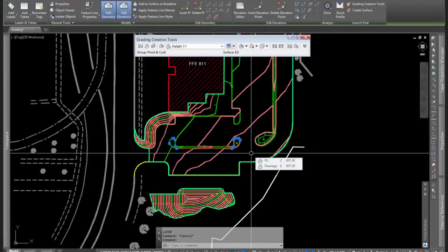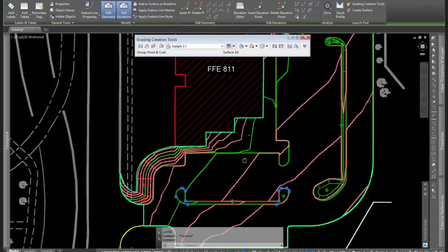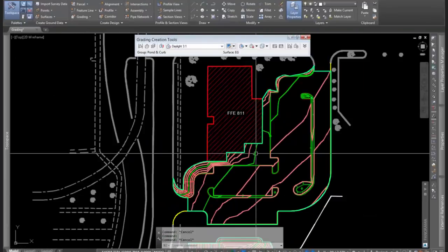So just one question that came in here: why don't you keep all the feature lines together right away? Why not avoid the pasting? Because what we don't want is feature line interaction between the curb lines and the drainage feature lines. What I want to be able to do is to keep that independent. If we start putting those feature lines from both of those in the same site, some of this interaction that we have right here, where I can put an infill in there.